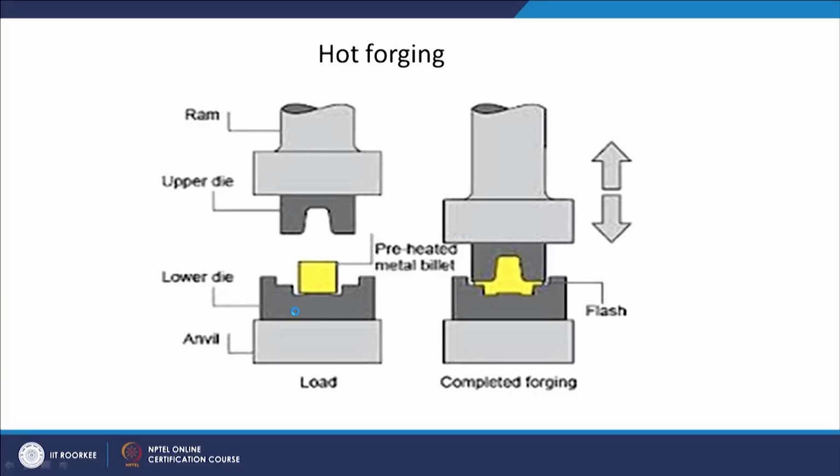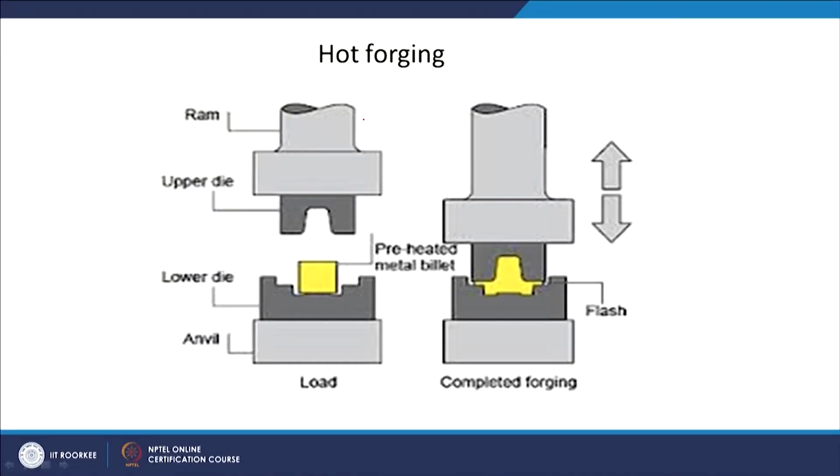The next process is what we call hot forging. So, very simple process, basically there are two rams. This is a fixed ram, then there is a moving ram here, and then you kind of bang the material at a very high strain rate, and you can choose the strain rate depending upon the rate at which you are hammering the material.